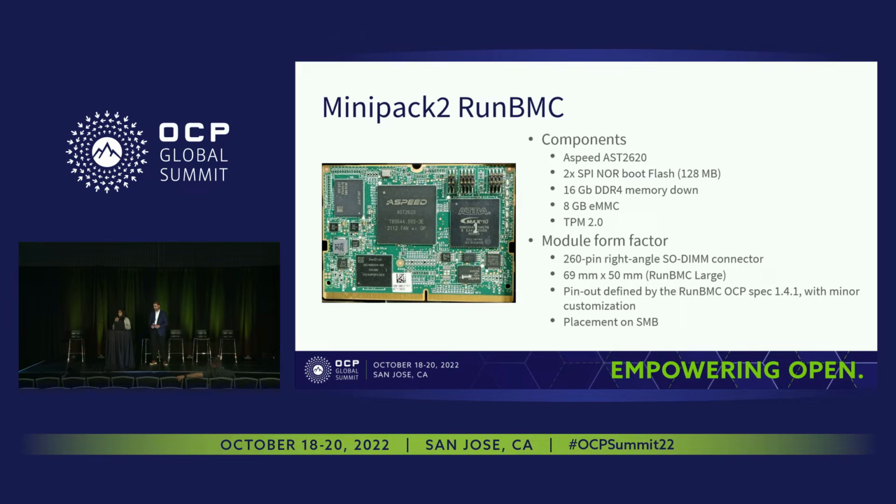So this slide goes over our specific Minipack 2 RunBMC, and I want to highlight a few things. We opted for on-module SPI boot flash. That's one of the scenarios that the spec describes, and we did that so that our BMC module could be relatively self-contained. The other key thing that I want to highlight again is that we use RunBMC large form factor,